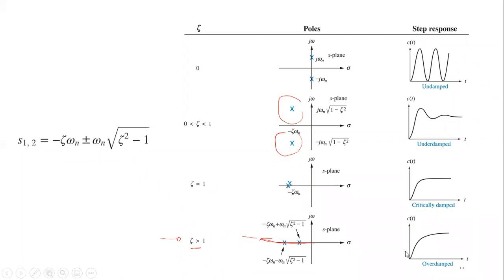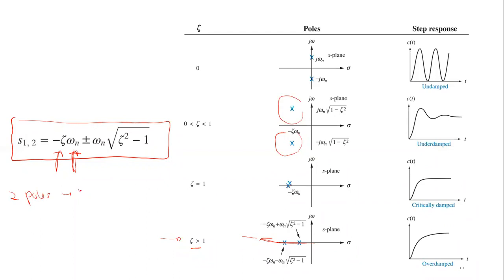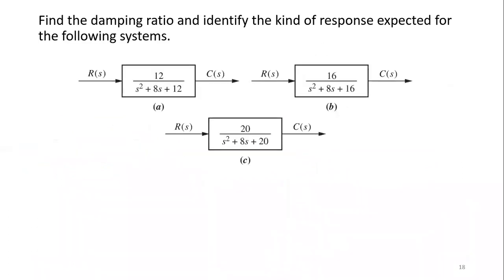So what else can you know? When you know the damping ratio and the natural frequency, using this formula you are able to find the two poles, pole 1 and pole 2. So this is the formula. These are the things that you need to know, because we're going to have second order systems, and you are expected to analyze the system. So far so good.